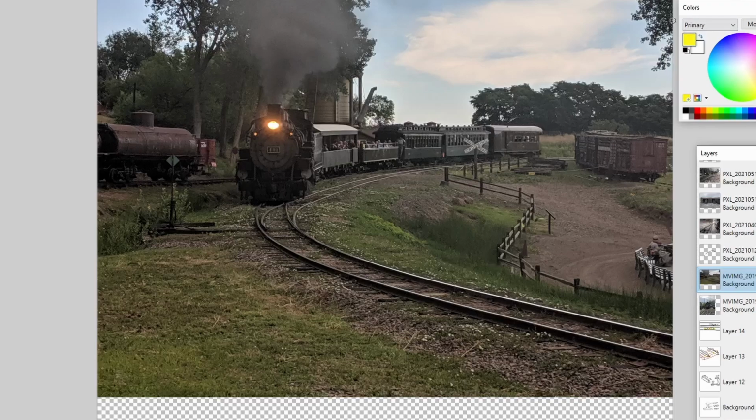So earlier I made a little mention about grade and how important grade is. Well, grade and ballast are incredibly important because we just talked about all this work to make sure that we could keep our rail anchored properly to our ties and transmit the forces of the train into the rail, into the tie, and make sure that things don't move. But if the track itself is not rigidly affixed to the earth, well, guess what? You're going to have a bad time. And again, that's what happened here.